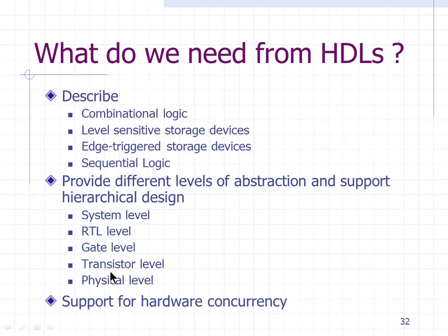So these two are combined at a transistor level, CMOS level. Gate and structural level is the same thing. RTL level is behavioral level. And nowadays, people are trying to go one level above Verilog, which is called system level design. Right now, Verilog as a language or VHDL as a language doesn't support system level design. So I cannot just tell it to implement the encryption logic and that's it. It will implement everything for me.